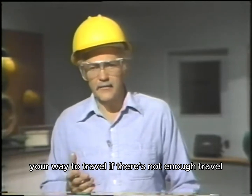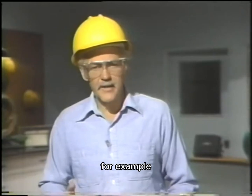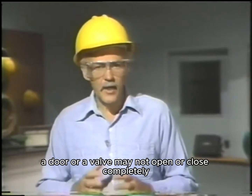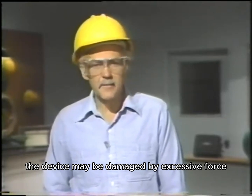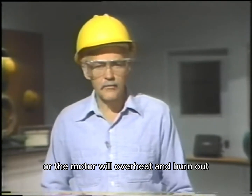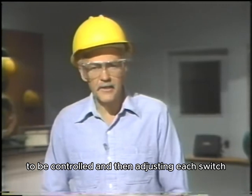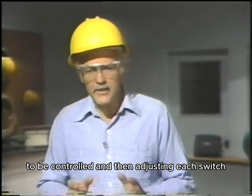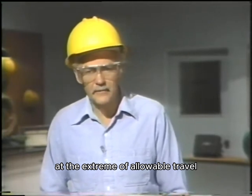If there's not enough travel, the device will not provide its full controlling action. For example, a door or a valve may not open or close completely. If a limit switch allows too much travel, the device may be damaged by excessive force, or the motor will overheat and burn out. Typically, limits are set by manually operating the device to be controlled and then adjusting each switch so it operates right at the extreme of allowable travel.